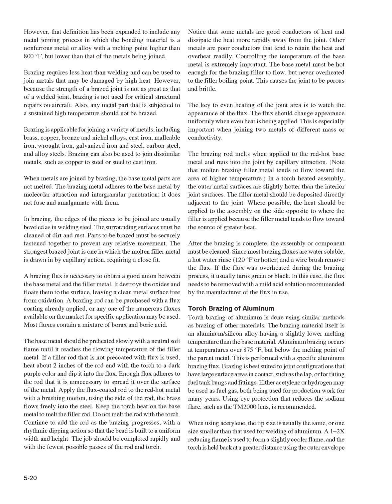However, because the strength of a brazed joint is not as great as that of a welded joint, brazing is not used for critical structural repairs on aircraft. Also, any metal part that is subjected to a sustained high temperature should not be brazed. Brazing is applicable for joining a variety of metals, including brass, copper, bronze and nickel alloys, cast iron, malleable iron, wrought iron, galvanized iron and steel, carbon steel, and alloy steels.